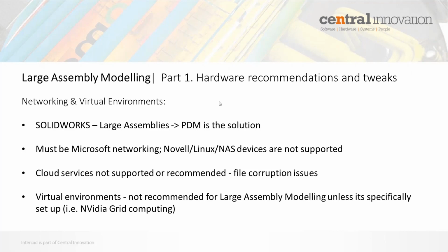If you aren't using PDM, if you're just working across a network, it's got to be Microsoft networking. Novell, Linux and NAS devices are not supported. The reason NAS devices aren't supported is because 90% of them, or 99% of them, use Linux as a base operating system on those devices. And Linux uses a different filing system to what Microsoft does, and the difference between those systems can result in file corruption. Similarly, cloud services are not supported or recommended for working with SolidWorks files.